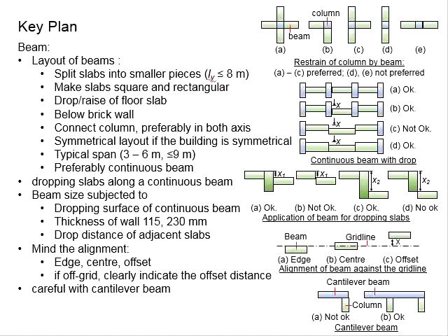The longer the span, the larger the weight of the slab, particularly when the slab is made of concrete with significant weight. When the span is more than 8 meters, there will be excessive moment, and this requires additional reinforcement. It is likely to become uneconomical due to the limited effective depth of the slab.